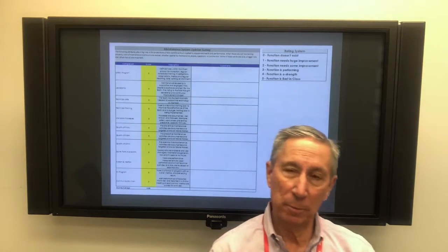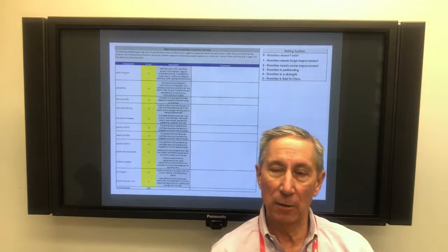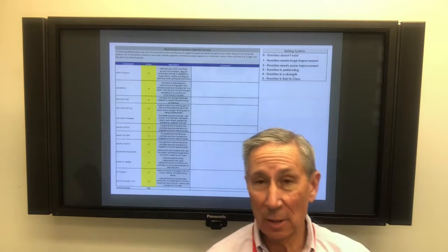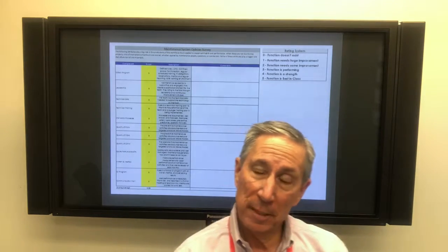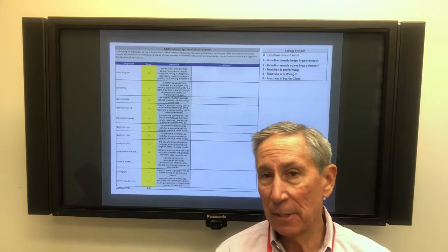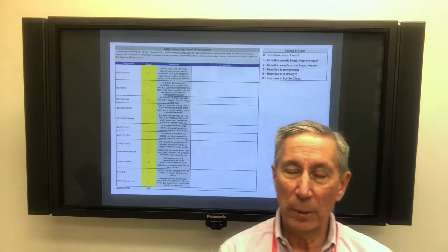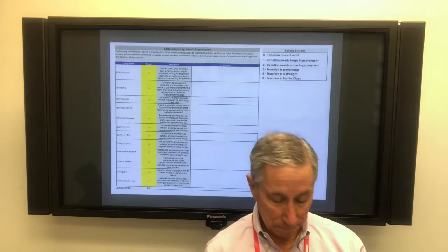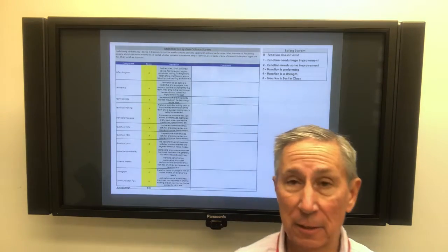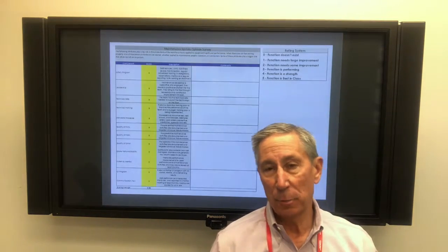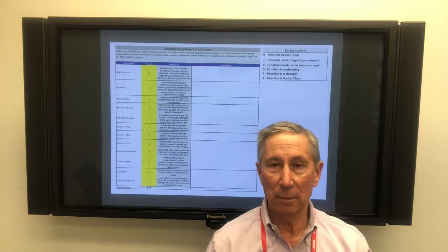You know, how we check spare parts in, how we check spare parts out, those kinds of things. Quality of the PMs, preventive maintenance: are the PMs written well? You can even take this conversation further about, are we implementing them? What's our compliance? Are we getting them done the way we should? Predictive maintenance. Some failures are what we call hidden failures, and you have to use predictive technology to uncover the fact that something's starting to fail.